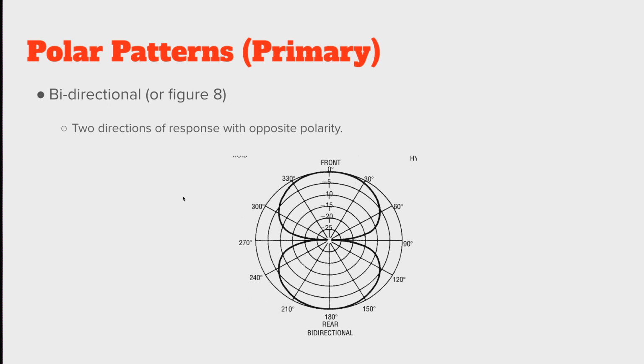On this one, we can see something called a bidirectional mic, or a figure of 8, or sometimes just called a figure 8 microphone. So here we have the on-axis response, the 0 degree point here. And we find as we start going off axis, the signal starts deviating from that 0 line and goes down towards the -5, -10 line eventually, and makes its way down until here at 90 degrees and at 270 degrees, we get what are called nulls.